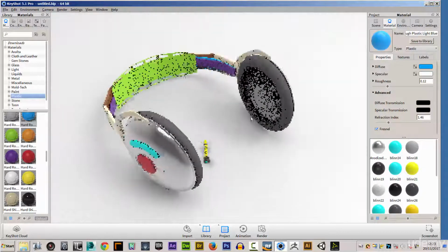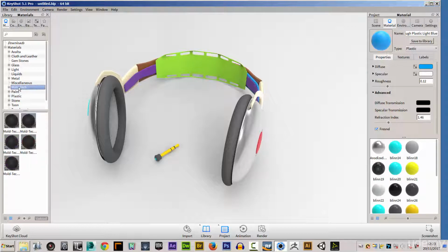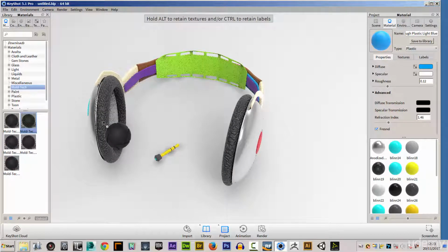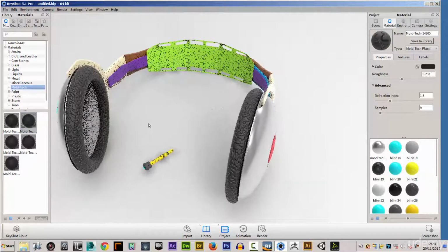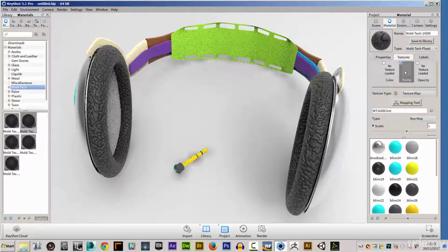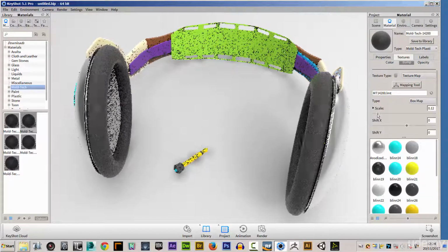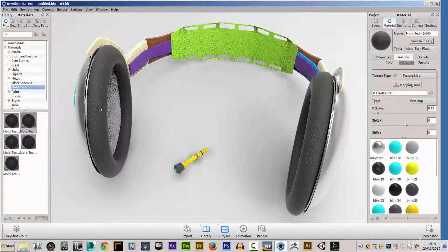Okay, now that's good. And also I want to pick something for this. Now I want a rubberized material, so I'm going to go to one of the Moldtec materials, which gives you this really cool look. So you can see there, it's got a bump map. Now, like I told you just now, if we go into the texture tab here, where we've got bump, we come down, we can scale this just to make it quite a tight texture. So there you go, it's slightly bumpy.